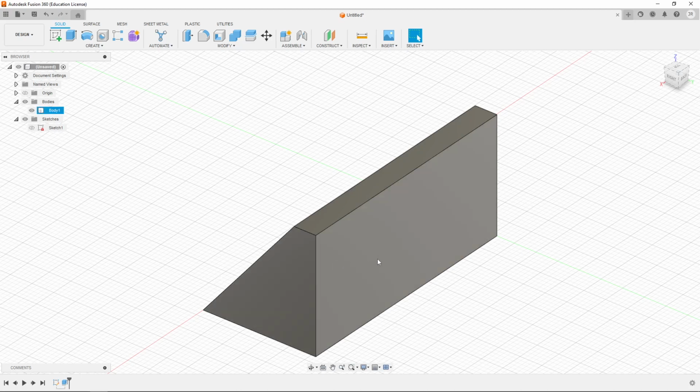The key difference is if you draw a sketch from a body, then the sketch is associated with it, and therefore if you do an extrusion, you may add to that body and merge them together, or cut from that body. If you did it separately as a new sketch independent of anything else, they might overlap and they may or may not be considered one object. And so generally speaking, if we're going to manipulate a body in some way, we typically would like to sketch on that body.